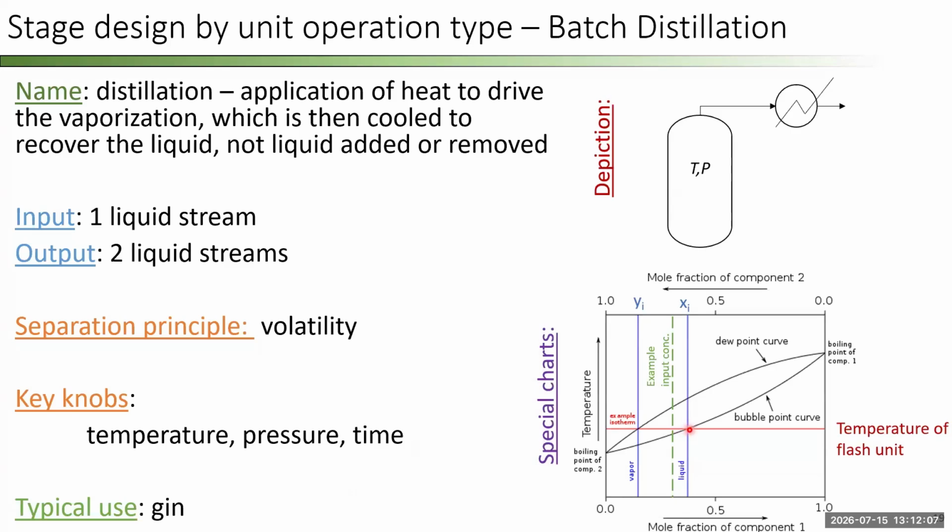So my concentration is going to shift. When I design this, I may need to change the temperature over which I'm operating with time to keep driving the change in concentration, or I'm going to hit some point at which I can no longer drive the desired change.